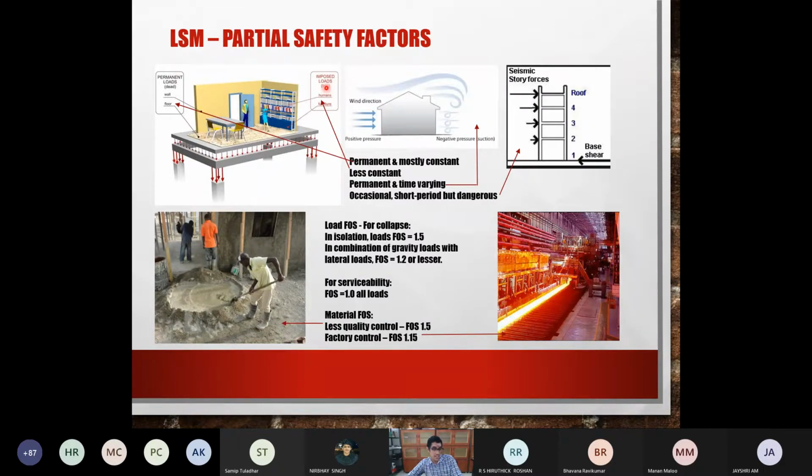There are other things known as live loads or imposed loads, which mean things which are going to act on the structure because of its usage. For example, if it's a normal building, you have humans and furniture. If you have something like shopping malls, then you have the racks as well, and the showpiece items. If it's a car park, you have the weight of the cars being parked. Those things which depend on the usage and can be moved are live loads.